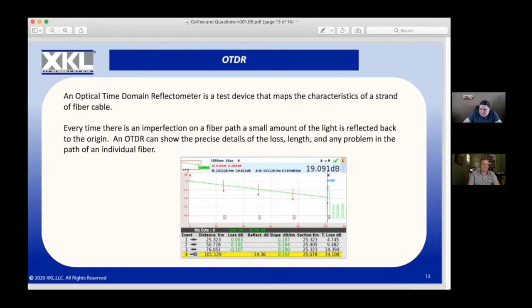Ron actually asked a question in there about 800 gigabit optical transmission on a dark fiber. That's something that's come out in the last year or so, and I mentioned that there are the DSPs and things. With optical transmission and the new frequencies, they always come out first with the manufacturers of the DSPs, the digital signal processors, and the guys who are actually making the optical components, the transmitters and the receivers and things.